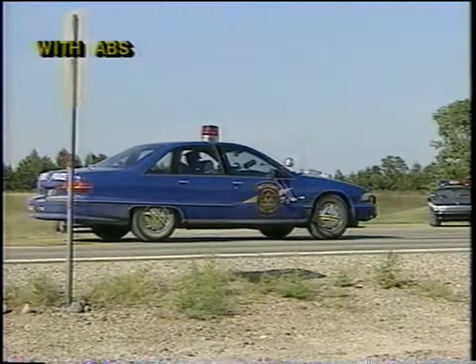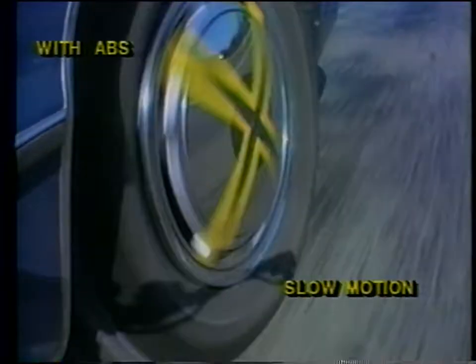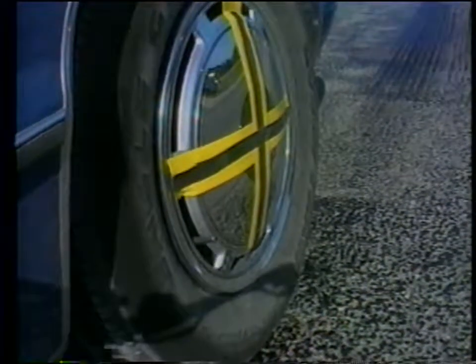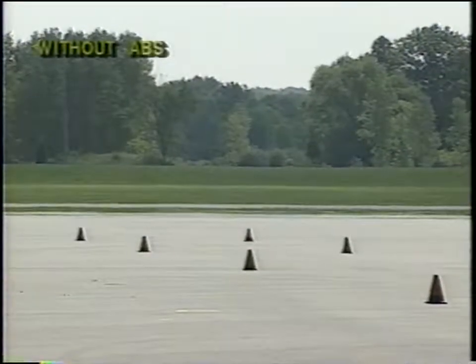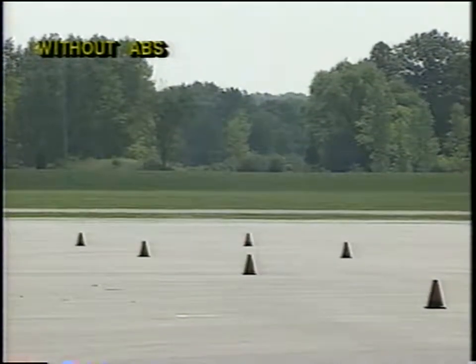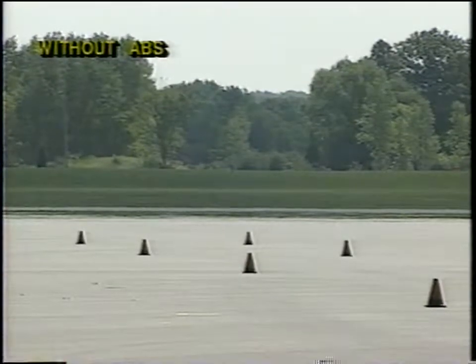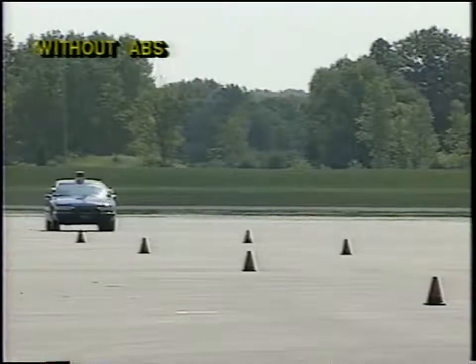In certain circumstances, such as going over a series of bumps or railroad tracks, with the brakes applied, ABS-equipped vehicles may decelerate more slowly. If this happens, maintain full brake pressure. Never pump the brake pedal. The next demonstration highlights the enhanced directional control of an ABS-equipped police vehicle. In this case, last-second instructions for a right or left turn are radioed to the officer as the vehicle approaches an obstruction at 50 miles per hour.